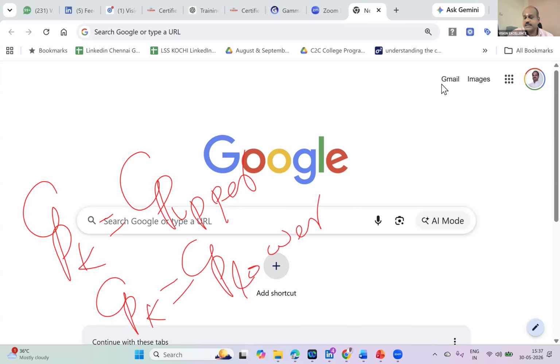Now, we just have to understand how to calculate the CP upper and CP lower. After calculating, we have to check whether the process is shifting to the right side or left side. If it shifts right side, then CP upper will be equal to CPK. If it shifts left side, then CP lower will be equal to CPK. All of you are clear with me up to this? Yes, sir.